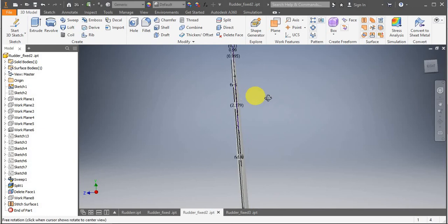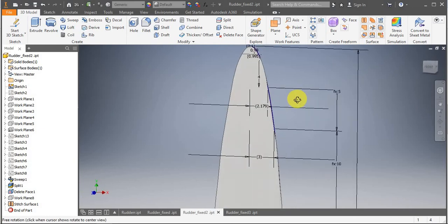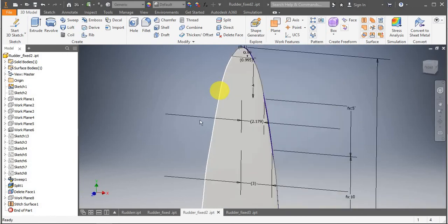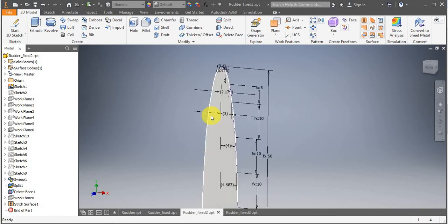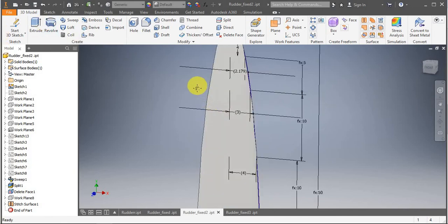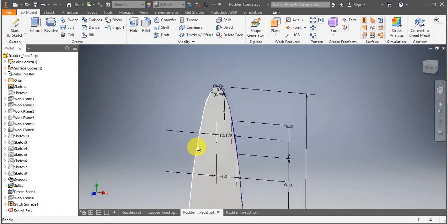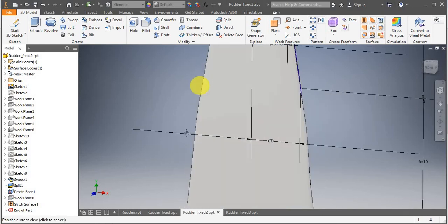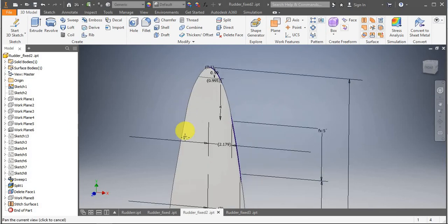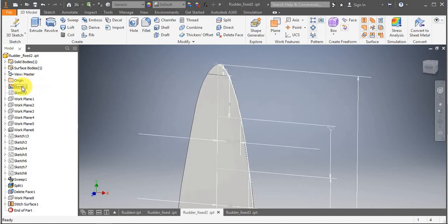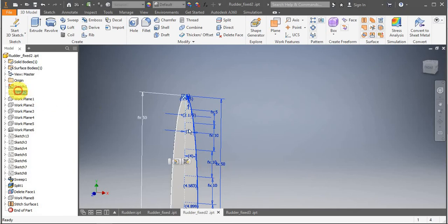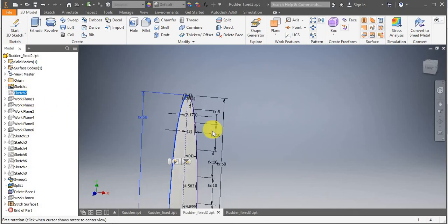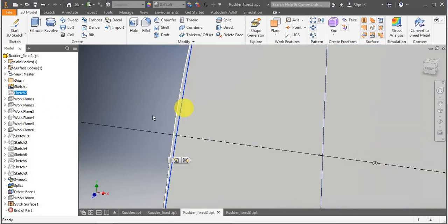This one actually seems quite good. However, because you can't use a path for the leading edge with the sweep tool, the leading edge doesn't have the original geometry of our sketch. It varies, as you can see.